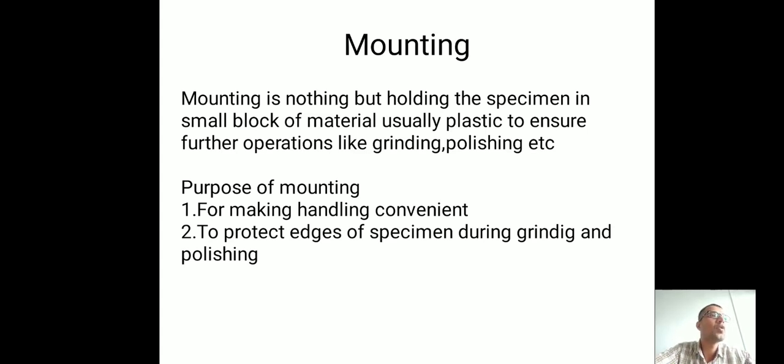It means we hold that section on plastic material, so here plastic acts as a mount. Why do we mount that small section? Because to perform further operations like grinding and polishing on that particular section.